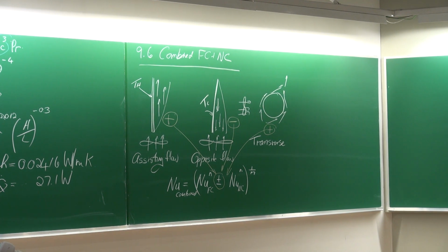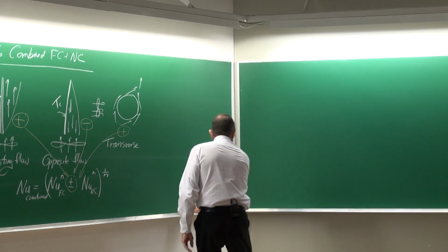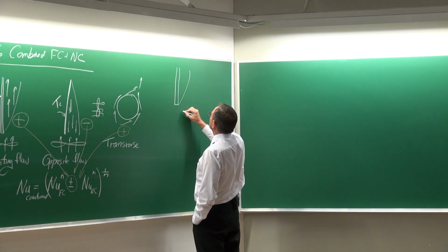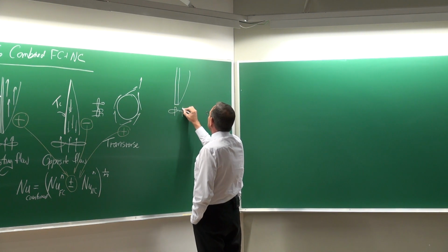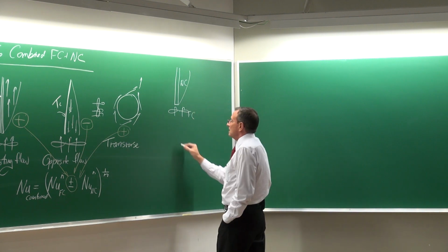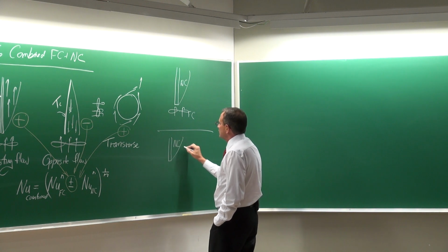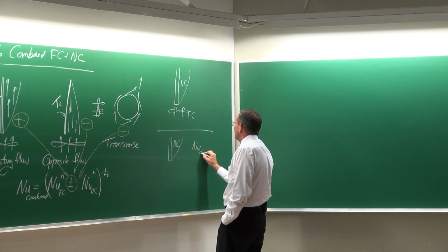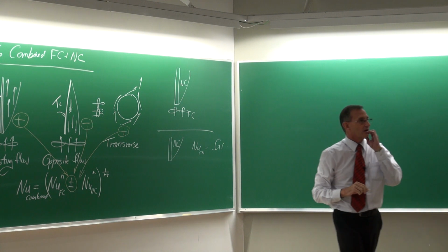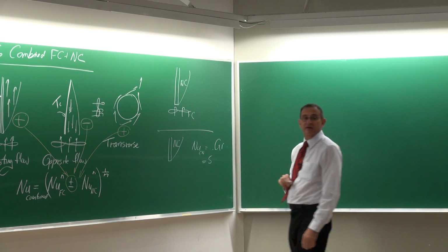Okay. So just to repeat, let's suppose you get a problem like this in the exam or the test. Here's the fan, forced convection, and there's natural convection. So natural convection and forced convection. Then you're first going to look at the plate and you're going to get the natural convection Nusselt number first. And it's going to be a function of Grashof number, etc. So you're going to calculate it. Let's suppose it is equal to 5, which would be a very high value.